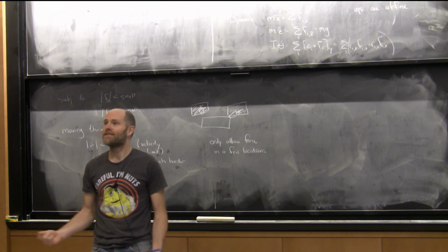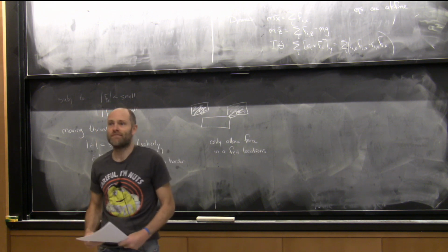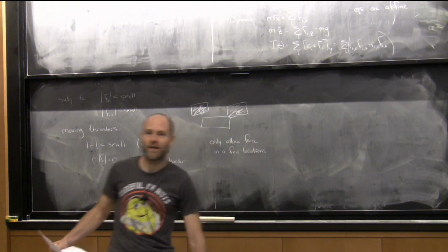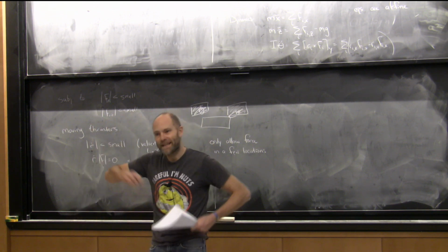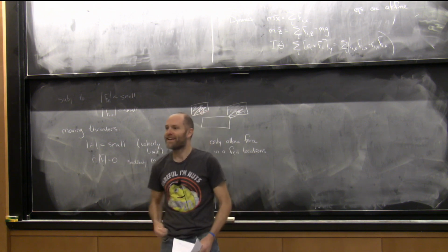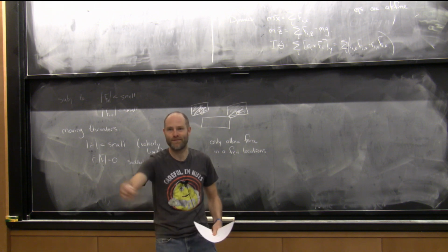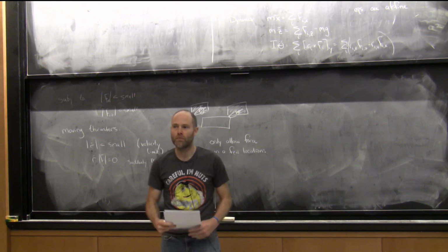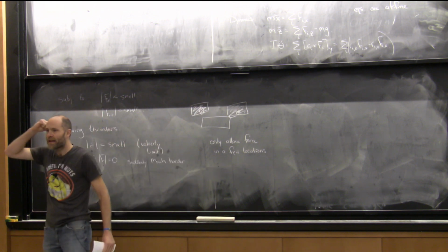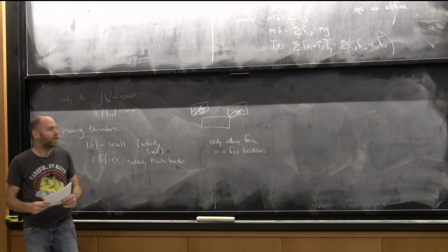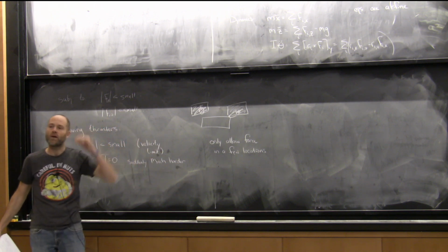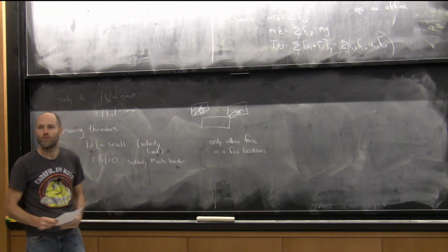And your job is to figure out how to move your center of mass by planning out, I'm going to push on this for a little while, I'm going to push on this for a little while, push for this for a little while. And if I can schedule that series of locations to push, then I can ultimately get through the level and succeed, right? That's a very different view than a compass gait. But actually, once you get enough degrees of freedom, I think that's the most relevant problem. That's the right way to think about how to make a walking robot move around. Okay?